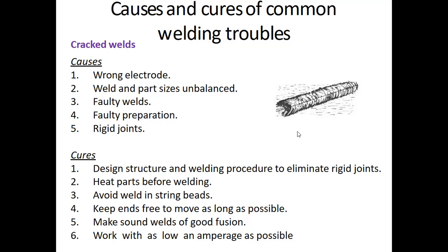And keep the ends free to move as long as possible, right? Ends, what we are starting and ending like that. Keep ends free to move as long as possible so that the stress concentration that is happening will not lead to cracks. Make sound welds of good fusion, right? Work with as low amperage as possible. Basically, ampere as in current, right?